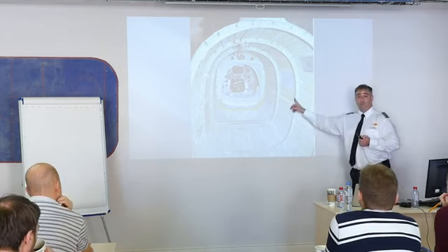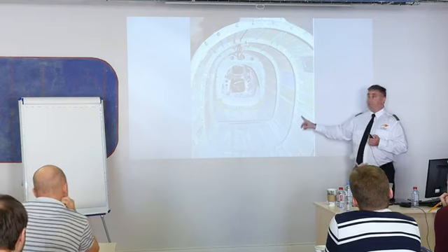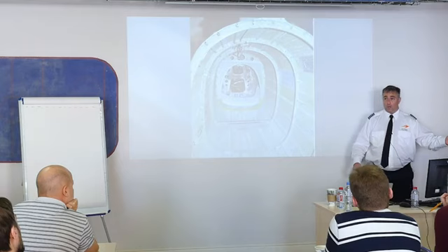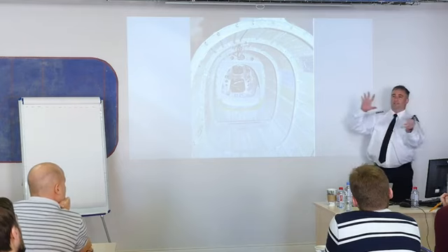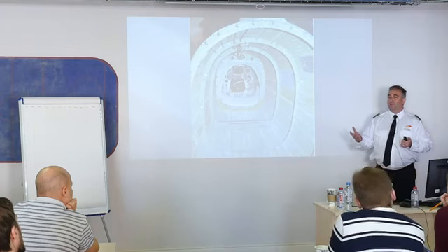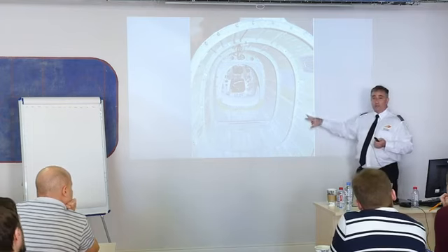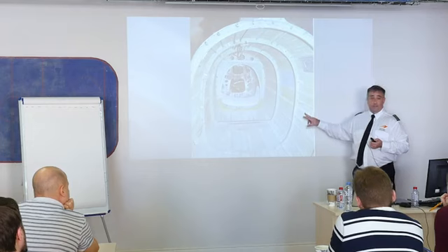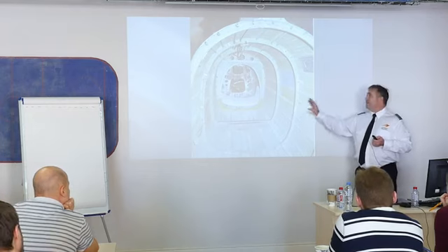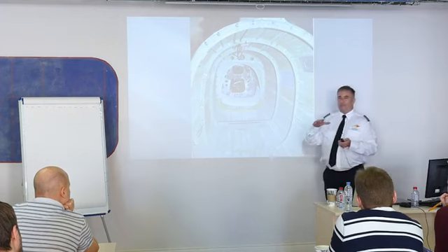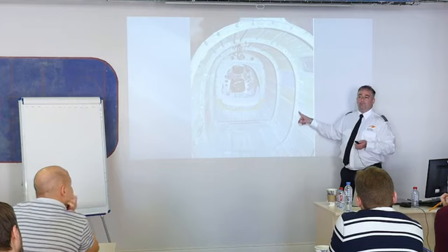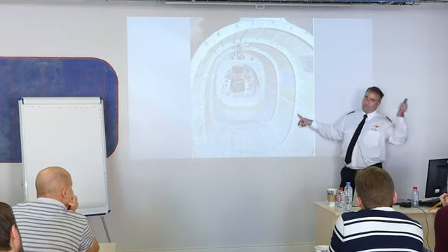It's built out of plastic, and it is a monocoque design airplane. So it does not have longerons and stringers. Instead, all it has is a rear bulkhead and a firewall. And all of the skin maintains the flight loads as we fly through the air, whereas here, they're shared by the longerons and the stringers. Okay? This is a very lightweight design, but if you think about how the sheet metal design works, remember the